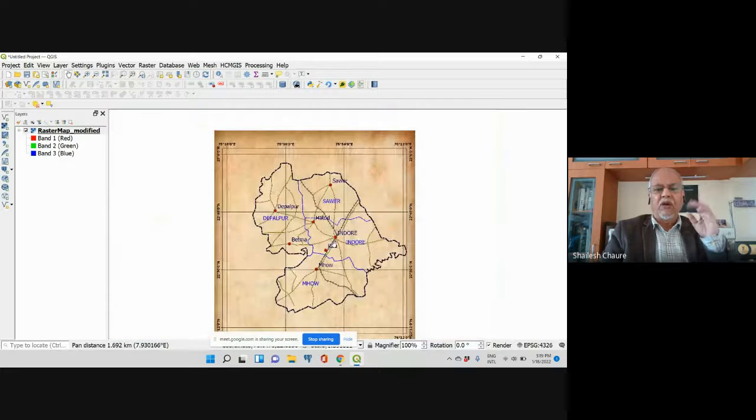So what will happen now in AutoCAD, when you want to create the data, you will create a file, save it as a mydata.dwg, and in that file itself you will create these 4 layers. But here in GIS you cannot do like this. Each shape file will be able to hold only 1 layer. So if you want to create 4 layers, means you have to create 4 separate shapefiles.